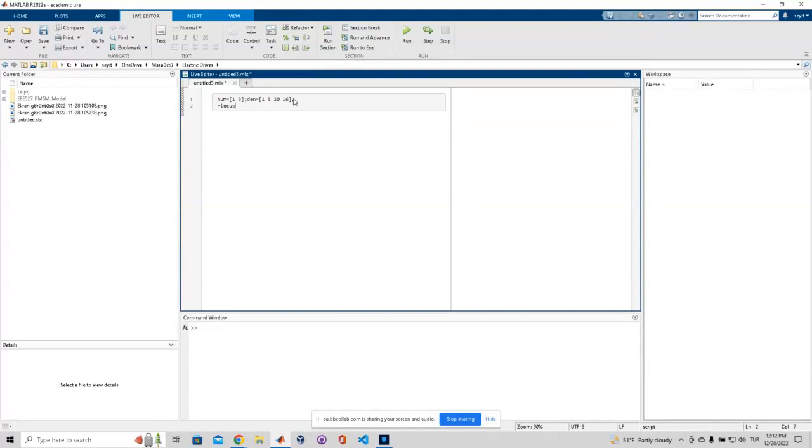First, you define your numerator and denominator. Inside the root locus function you just write your numerator and denominator, and it will plot your root locus diagram. And you're going to define a v vector for the scale of your graph. And then let's say 6. And then the v axis.